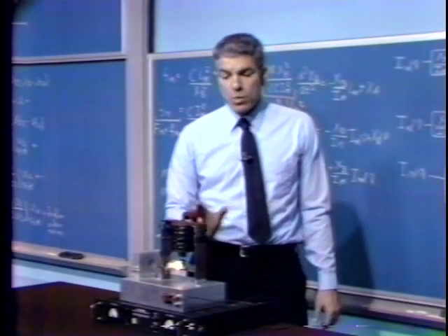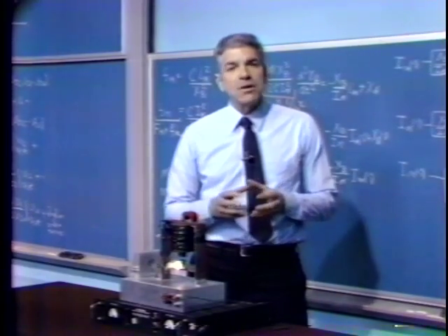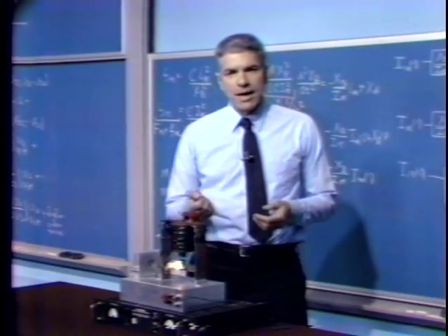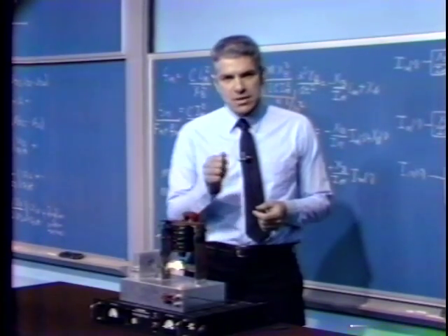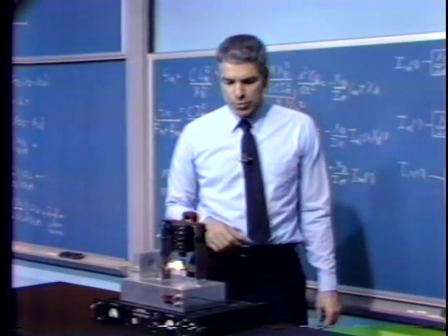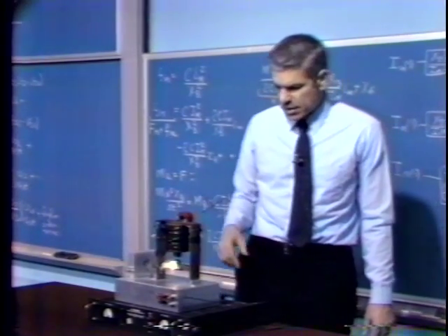Once we're to that point, we get it stable in an absolute sense. The rest of the sort of quote optimization goes very, very quickly, because we can now look at a transient for the system and see the effect on the transient of adjusting A naught, of adjusting zero location, and very rapidly improve the performance of the system that way. And that's exactly the way I did design the system.